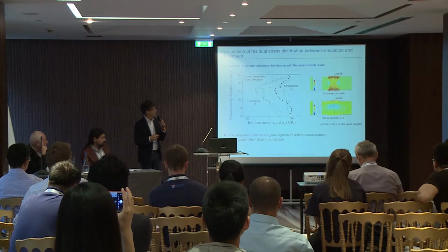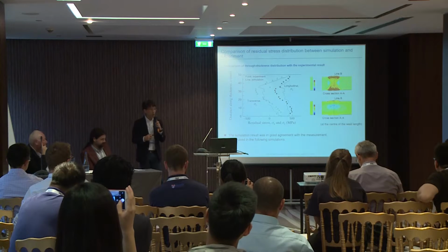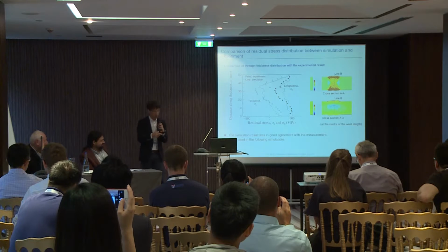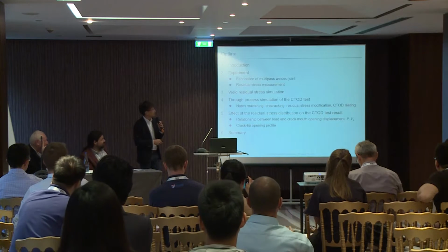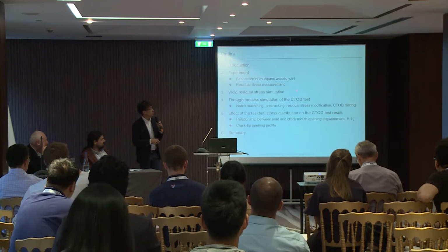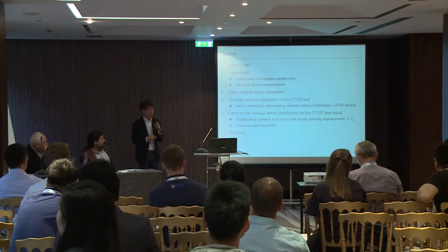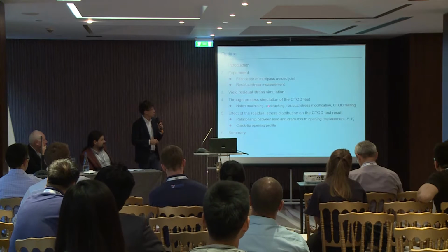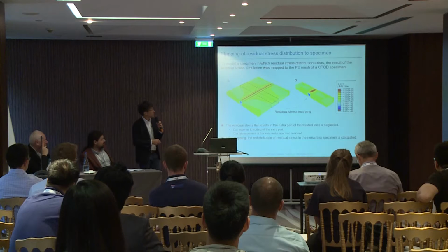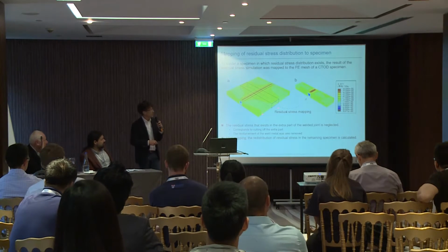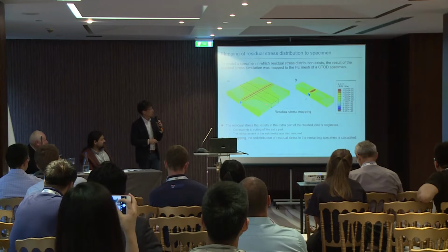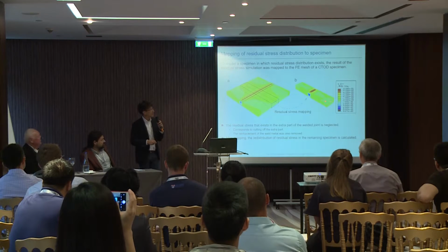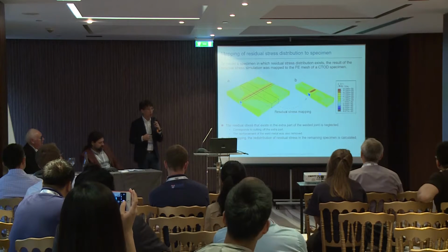Reasonable agreement between experiment and simulation is obtained. So now we have the welding residual stress distribution from numerical simulation, and then we go into the through-process simulation of the CTOD test. At first, the residual stress distribution obtained in this welded joint was applied to the specimen for CTOD testing.